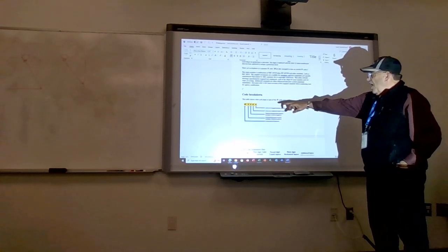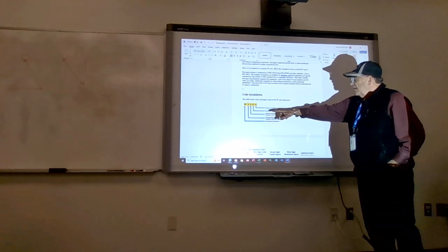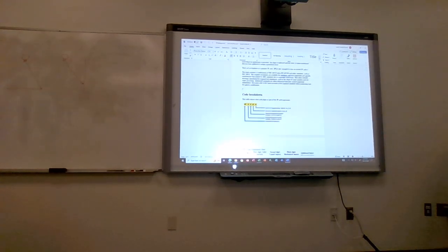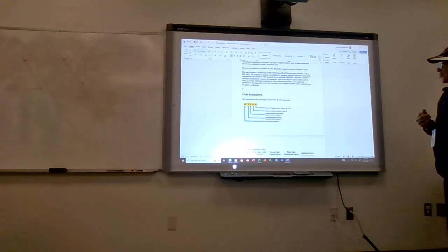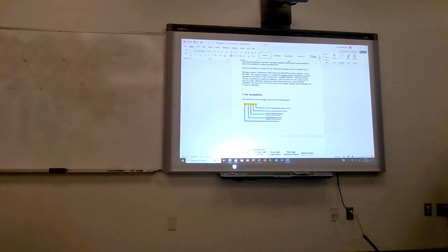The first number is the degree of penetration. So IP2 would be lots of things can get inside of the fixture, like your finger. IP3, maybe a screwdriver. Maybe IP4 is a smaller object, but IP5 would be very difficult to penetrate.